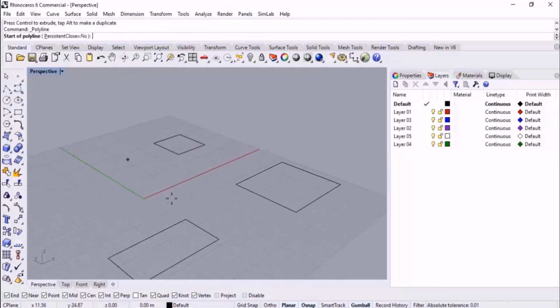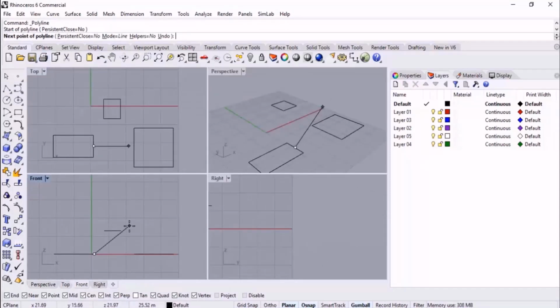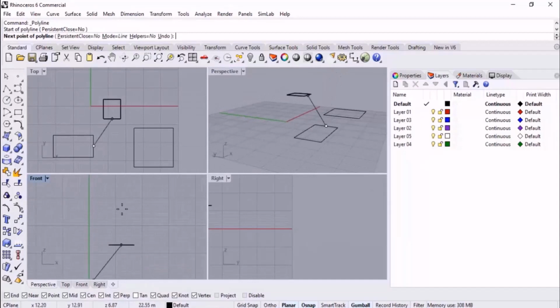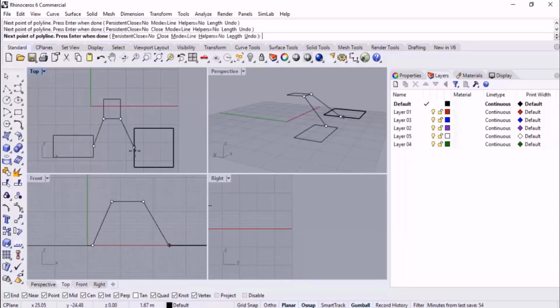Let's check it out. From the midpoint, the planar is enabled. As you can see, watch this part. I want to follow the process this way, but as soon as I sketch the point, I snap it to the end point of the rectangle, after that the planar is no longer effective. But in this condition we can consider the role of project.